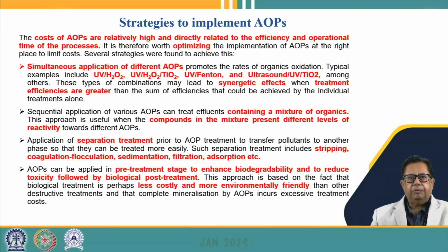Similarly, consider the simultaneous application of different AOPs, for example UV or H2O2, the combination of UV, H2O2 and TiO2, or ultrasound, UV and TiO2. These are systems which can lead to a synergistic effect. This means that they can enhance the efficiency of the system compared to the individual treatments alone. Efficiencies are much higher, as it can result in higher generation of •OH radicals when they are present in combination rather than alone, because a synergistic effect may be induced when the different types of advanced oxidation systems are present in combination.